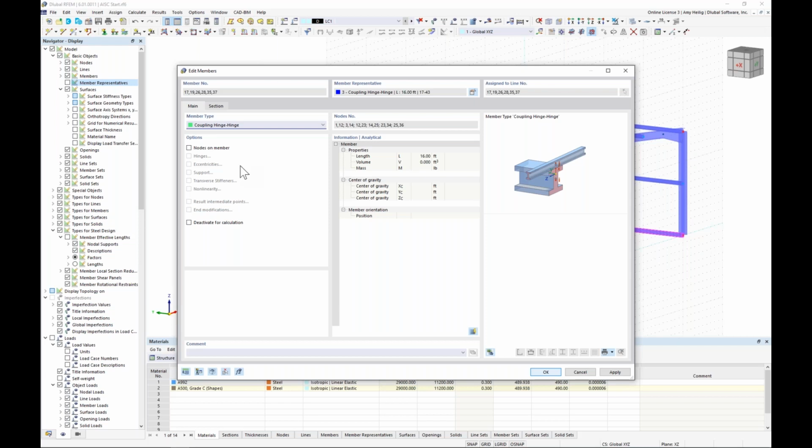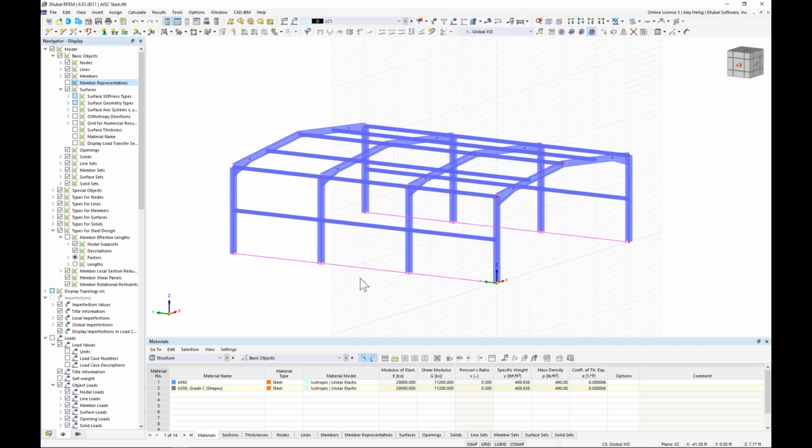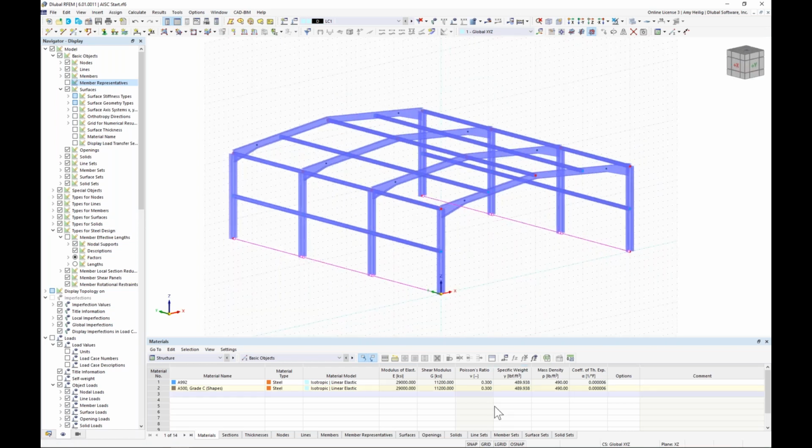All of that's handled internally with a very high stiffness, and a hinge is simply going to release the moment at either end. And the reason why I'm doing this is we will be defining surfaces along the facade walls for the entire structure, and I want all of the loads that are here at the lower part of the structure to be transferred back to the bottom of my columns and into those foundations. And we'll see that once we generate those surfaces.